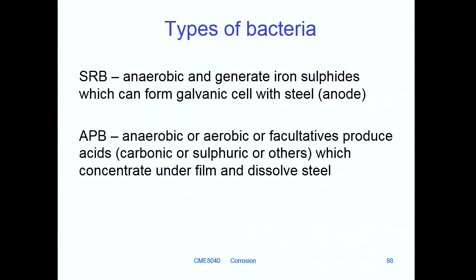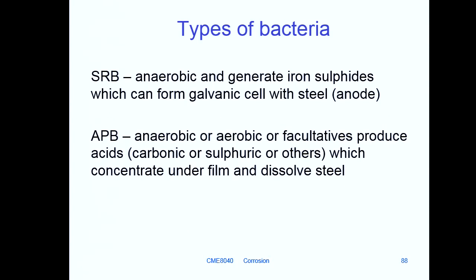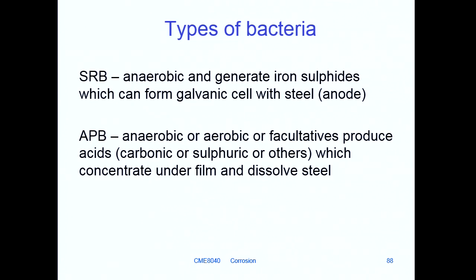And this is not dissimilar to the sort of thing that happens in ordinary steels where you've got sulfide inclusions. If you've got a steel that isn't very clean in its production, then it may have manganese sulfide inclusions in it. And what you find is there are areas where you begin to get pitting on the material if it's exposed to a solution.